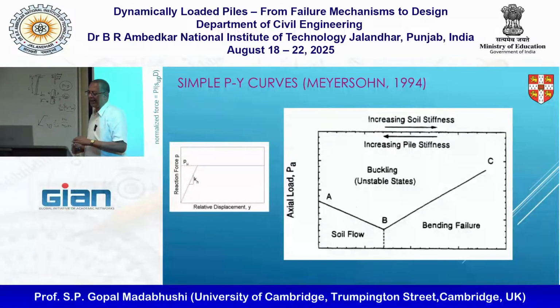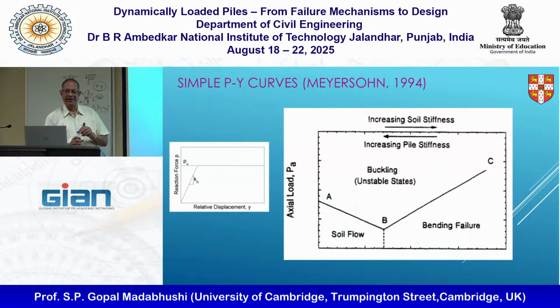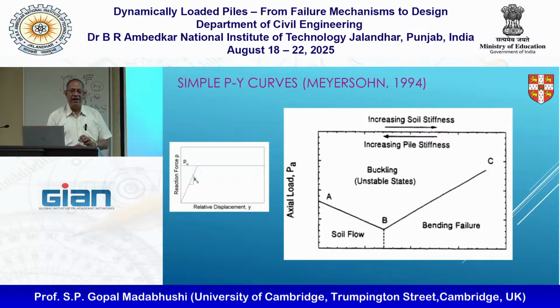This is quite a good observation: when the piles start to move, the initial stiffness can be big, but as they continue to move, it will reduce the force because of lateral spreading, liquefaction, and the rest of it. And then you reach some residual value at the end.